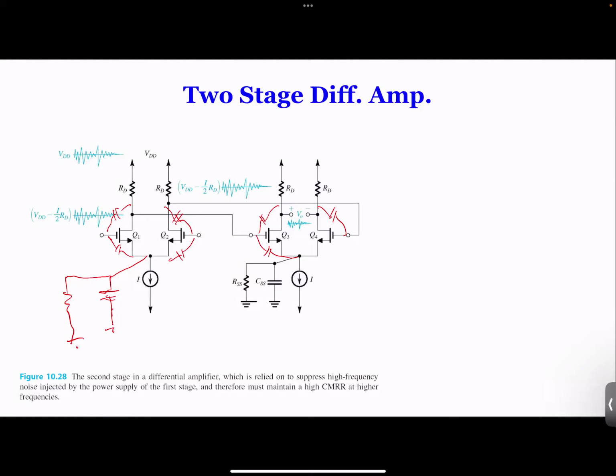However, the problem is that our typical small signal is also in the millivolts range. Okay, that's the problem, right? I don't care about 5 millivolts to my 5 volts, it's only like 0.1%, not a problem. But if it's picked up by your amplifier, it's comparable to your input. So your input is a few millivolts, it's picked up. Okay, and then this gets amplified.